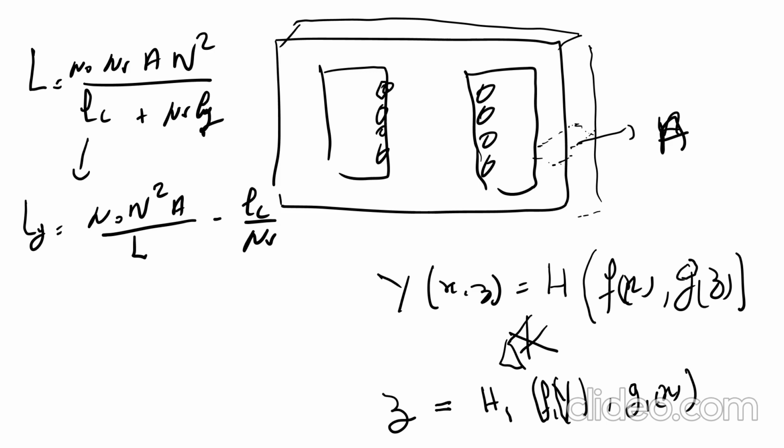The same thing will happen to the energy capability of the gap: it will increase by the same factor because it is the same cross section here. So you don't need to change the air gap at all, because if you change the cross section, your magnetic core will not saturate, it will be able to handle that energy, because the energy capability of the air gap will increase by a factor of X. The same thing for the magnetic core. So this is my intuition.